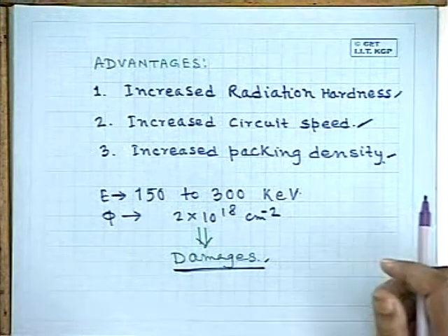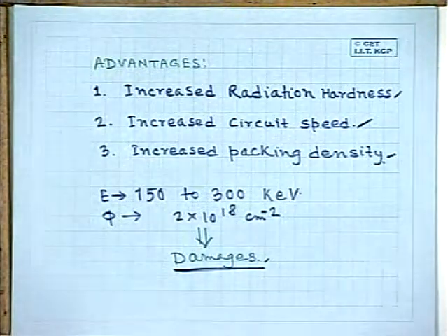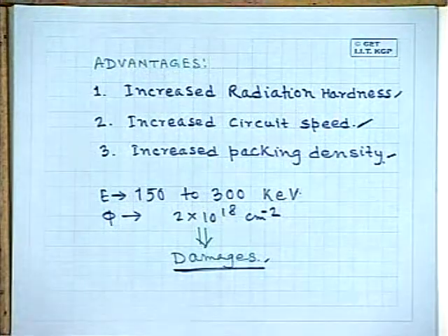There is a technique, and that technique is known as high temperature implant. There the substrate is kept at a higher temperature in the range of 400 to 500 degrees centigrade. In normal implantation, we don't raise the substrate temperature. The temperature of the substrate will increase because of the impact of the ions on the surface of silicon. But here, in addition to that, before implantation the substrate is heated to 400 to 500 degrees centigrade. So that high temperature implant will obviously reduce the surface damages.